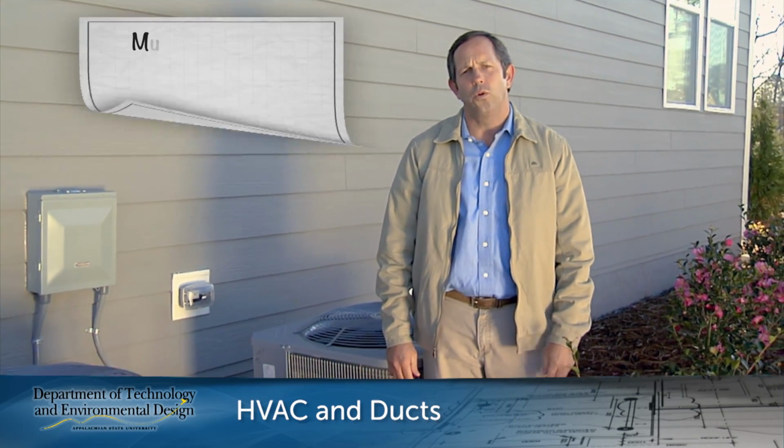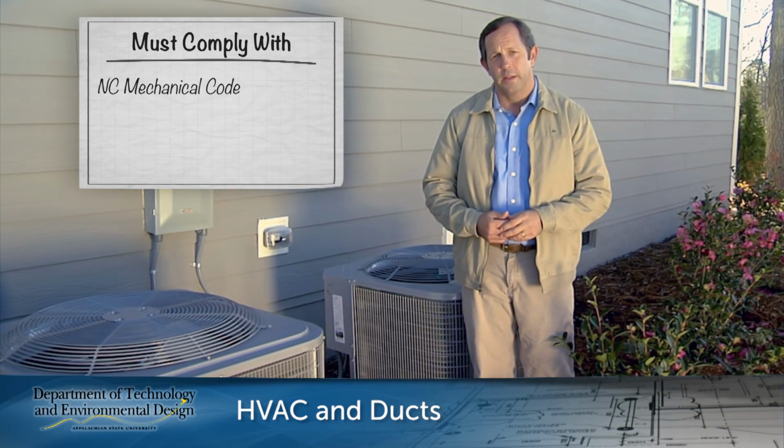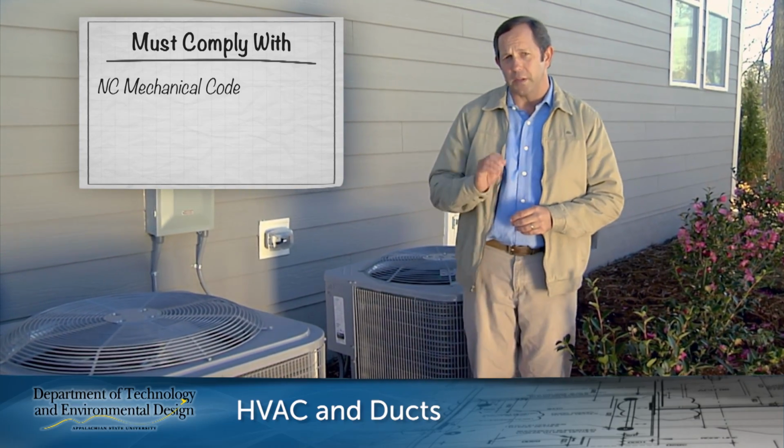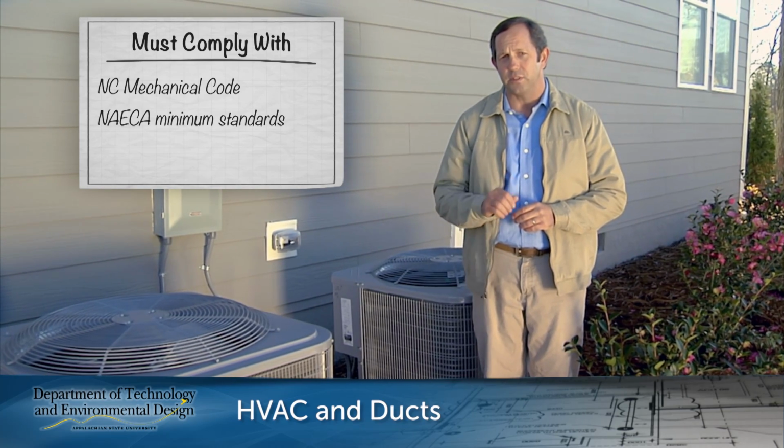What do you say we get into HVAC ducting, equipment, and testing next? Heating and cooling equipment must be sized in accordance with North Carolina Mechanical Code, and the efficiency of these units must comply with current National Appliance Energy Conservation Act minimum standards.